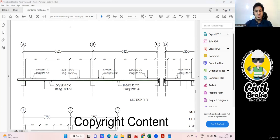So top left, this is the distance they have given, from the beam outer to here. This is the beam, from the beam outer to here, this much you have to go. It is 1650. This was a middle span which I did on both sides. From the beam inner to this side it is 1650. From the beam inner to this it is 1550. And this end was the C end, no? From here it is 1550. Got it? Able to understand? In this way you are supposed to do the estimation, I mean the bar bending schedule.